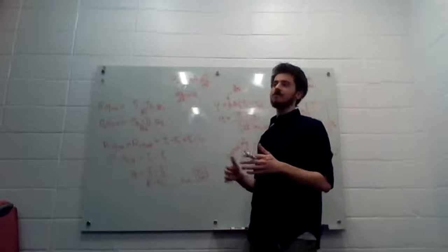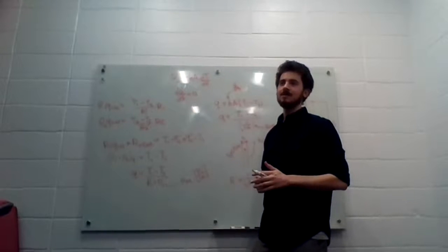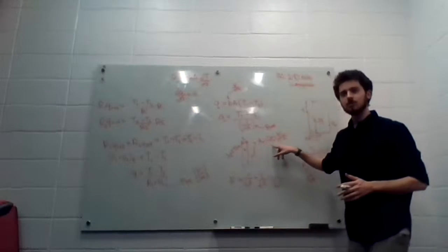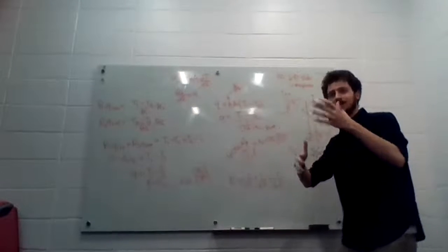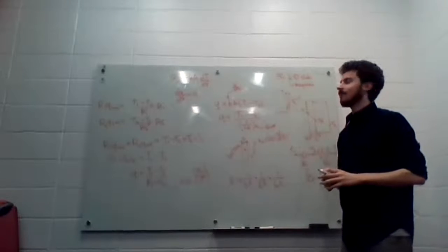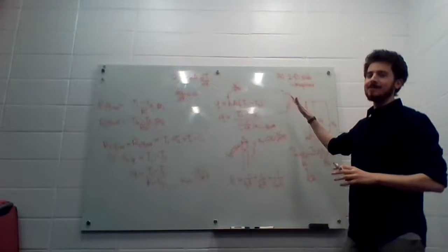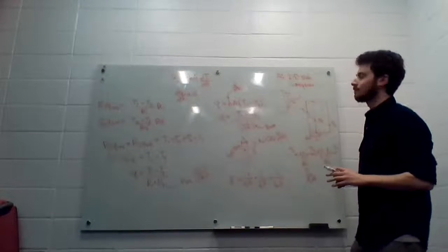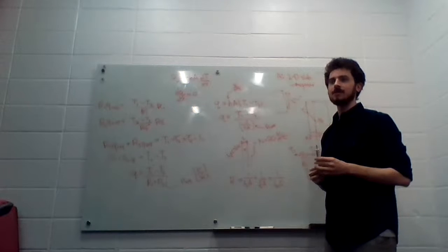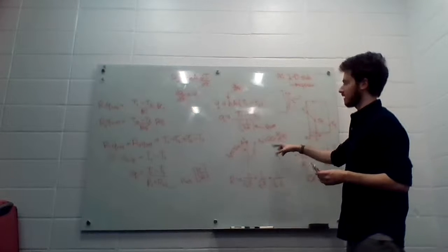And then we'll ask, what if the outside temperature is 0 degrees Celsius? This H equals 20 will depend on the velocity of the fluid near the wall. So this is a bold simplification, but it's a very useful one for now at least. And later on, we'll really interrogate these coefficients.